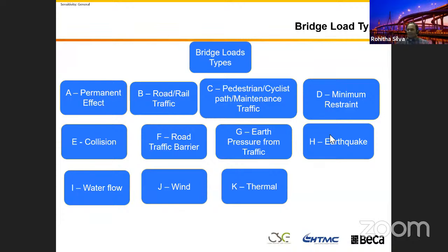These two combinations, but you don't want to combine the ultimate limit state combination of dead load and traffic with your earthquake, because that is also an ultimate limit state event. We design for a very short return period. So therefore, you can consider a different load combination. The permanent effect is always there. The serviceability limit state condition in your bridge due to traffic with the earthquake, you can consider that in your bridge design. You can make that decision according to the purpose of the bridge.